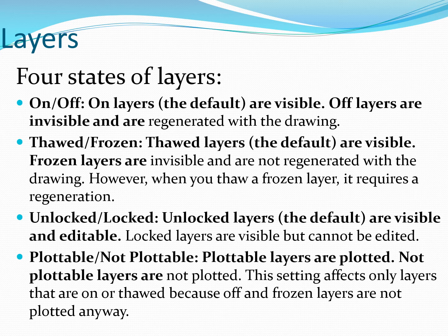Okay, so for the state of the layer: on, off. On layers by default are visible. Off layers are not visible and are not regenerated with the drawing. Thawed or frozen: thawed layers are visible, frozen layers are not visible and are not regenerated with the drawing. However, when you thaw a frozen layer, it requires a regeneration.